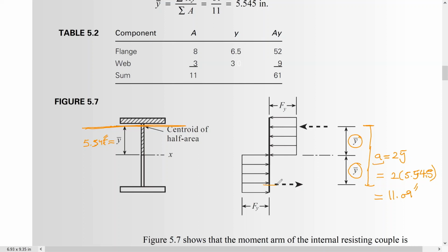So right now Z, as we know, is equal to A divided by 2 times a. And this is the cross-sectional area, this is a distance. They are different. A is 11 here times 2, because when we calculated the area earlier, it was just for this shaded section.